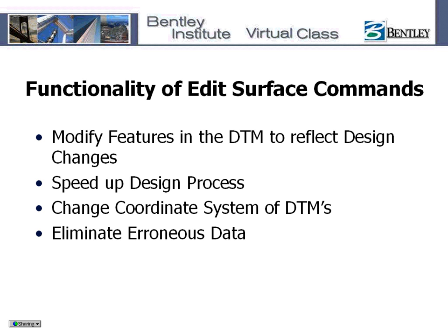Next, you can eliminate erroneous data from the surface. Examples of this would be removing long triangles along the edges of the surface that do not reflect where actual survey data has been taken, and also deleting incorrectly placed features within the DTM. The last function of the EditSurfaceCommands is that they manage DTM data. That's the bottom line. It gives the user the ability to adjust quickly when the scope of the project changes or any other changes occur within the project.